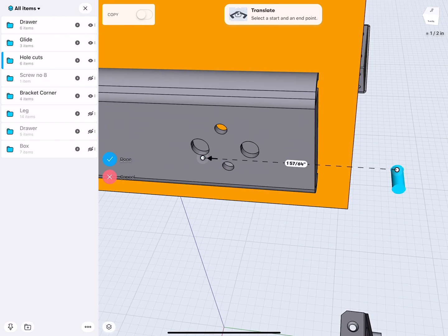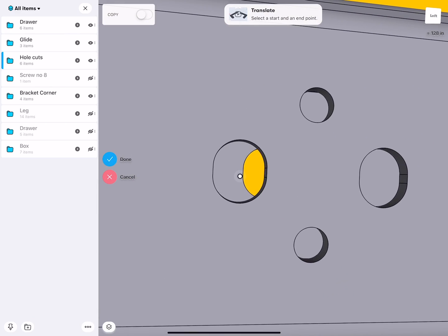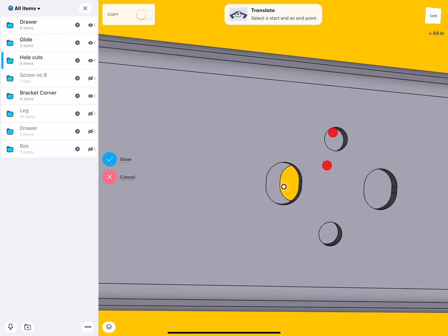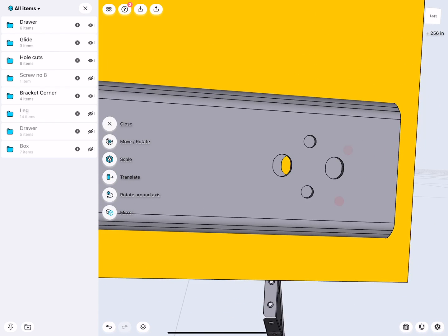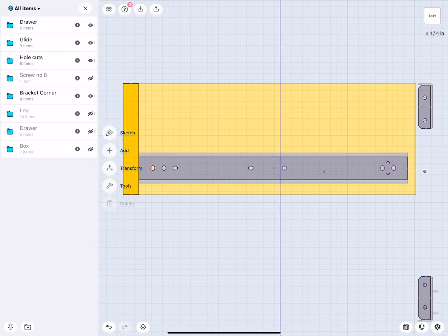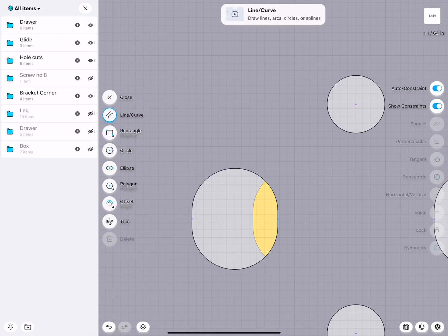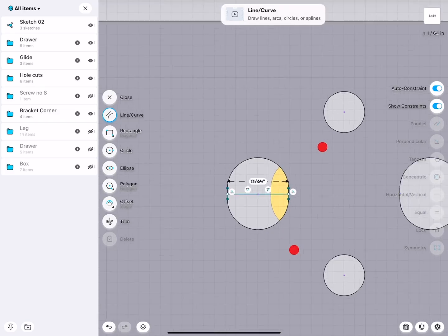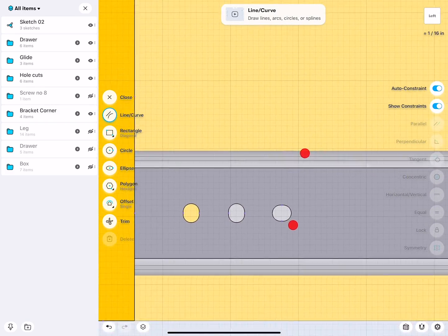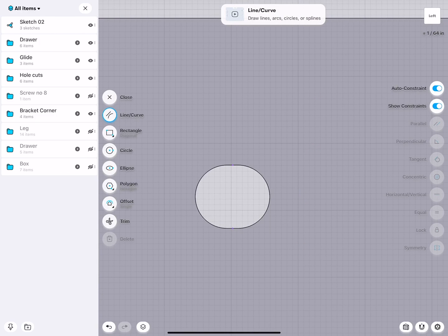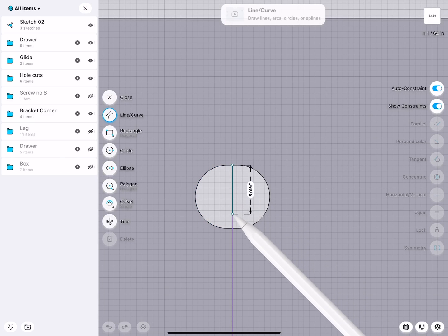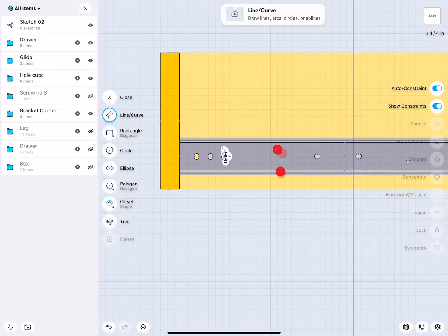there. So this is the arc center, but because we have a flat line there, this is a little bit more tricky. Here again, then we can select this face, double tap, and we simply will then create a geometry helper. There I have 2 midpoints. And the same here. Whoops, careful how you draw it. There. Okay, so these lines now I can use to snap to.